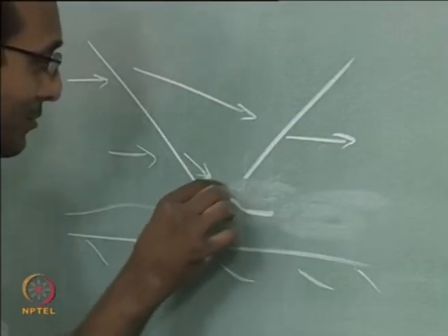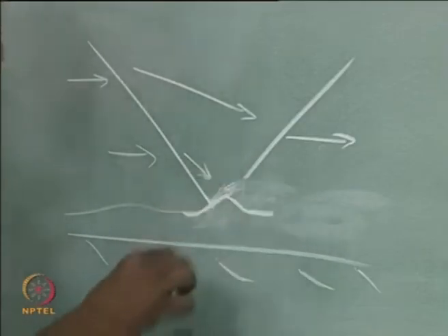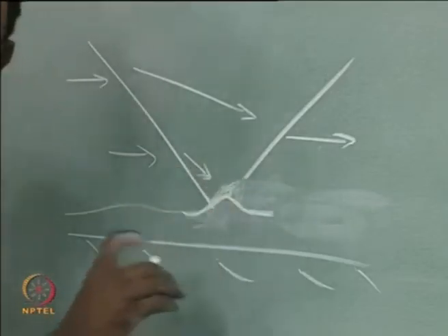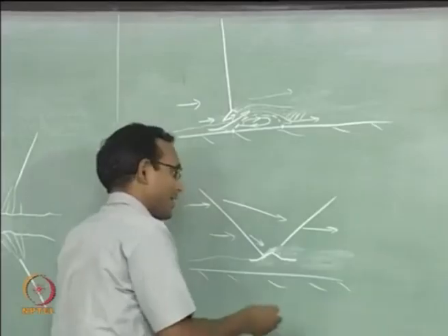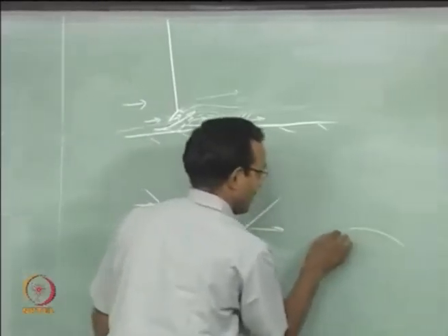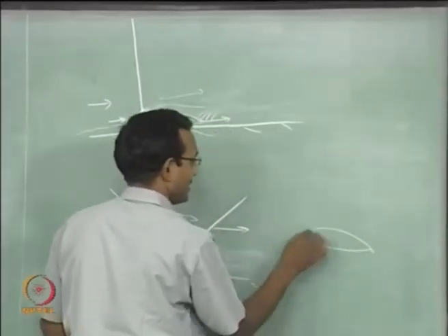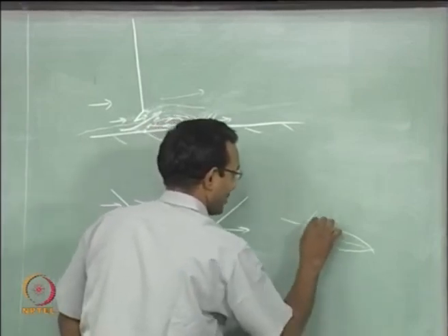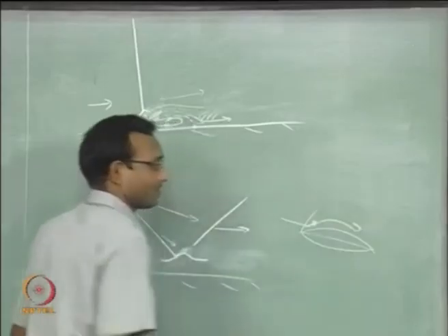So there is going to be a set of compression waves, they are all going to mix together, and there will be expansion waves after some time. Okay, because it is a smooth curve similar to the airfoil we had before. Okay, it is at an angle of attack, let us say. This airfoil at an angle of attack, flow is going to come here, and then it is going to see all kinds of things after this. It is going to expand after that.